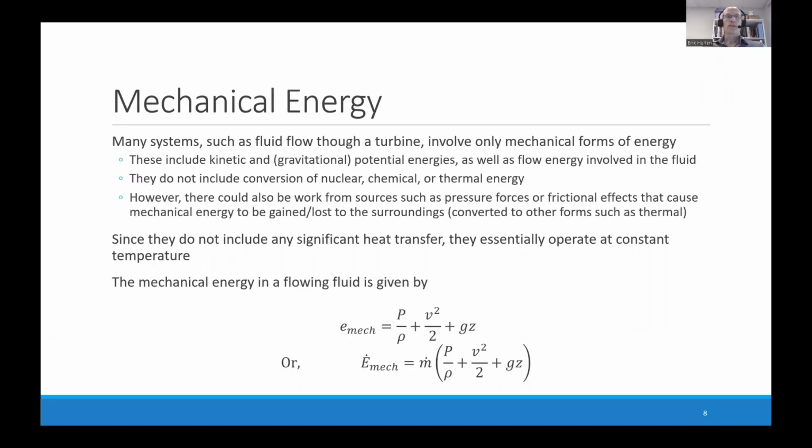Mechanical energy is comprised of kinetic and potential energies, as well as any flow energy contained in the fluid. This is most commonly related to the pressure. It does not contain any thermal or chemical energies. It could, though, contain other forms of energy associated with work, such as friction. Since there is no heat transfer involved, the system will remain at a constant temperature.